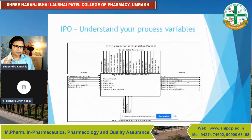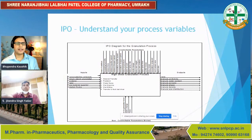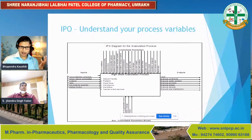Okay, so what we have here is a product which is using microcrystalline cellulose, sodium starch glycolate, povidone, water, and the granulation process here. Your variability can also come from your excipients. For example, the particle size distribution of povidone can obviously affect the preparation and the wetting time of the granulating media itself. In the middle you have your controllable parameters, which are the process parameters that you may have the opportunity to change. And during the design of experiments, you may be stretching them from one end to another end to generate more data.